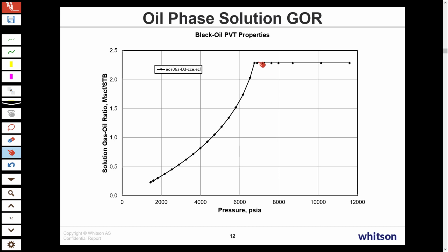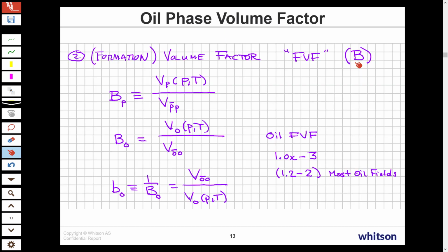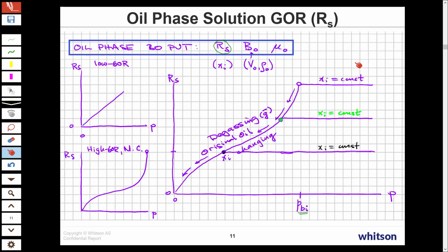Now, above the bubble point pressure, of course, this oil's composition does not change. But if we looked at this situation here where we go below the bubble point, gas comes out of solution, and then if we recharge the pressure of that oil, you'll be coming up with a different composition. So there's actually a series of these curves if you look at a reservoir process, for example.